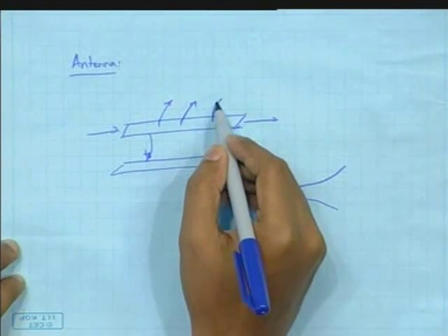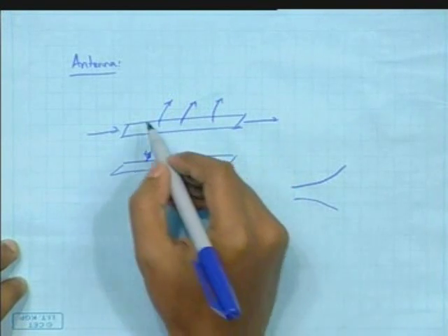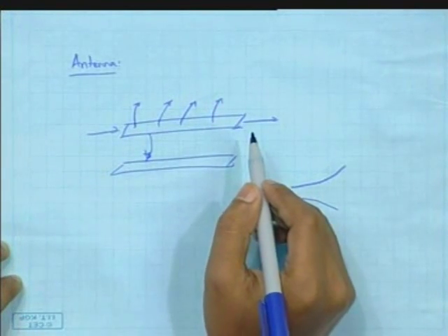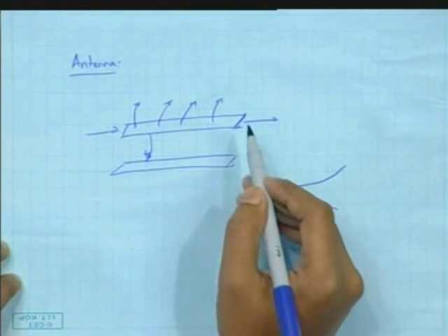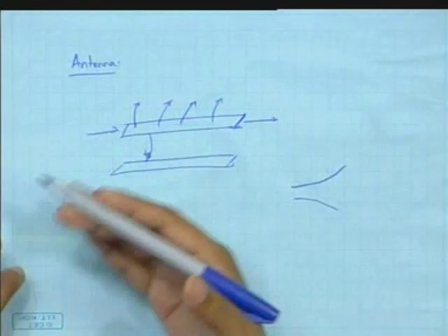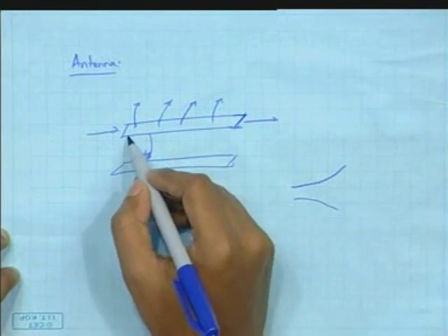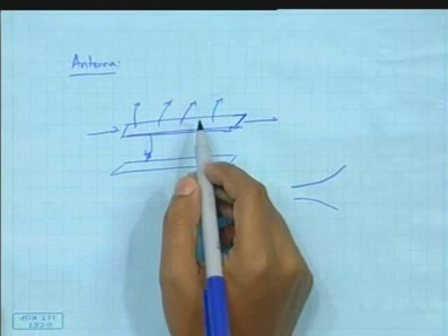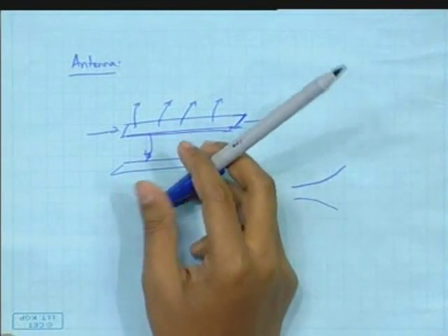So these types of antennas in general are not fabricated on silicon due to the higher dielectric constant of this material, and hence generally antennas are on a separate substrate, but it's on the same total package. So this is basically the summary of whatever microwave devices you will be using. You can have a brief overview, you will be studying, most of the electronics guys will be studying in your future classes. But it's good to know that when you design chips, at high frequencies you should be able to identify these effects, as not use very thick lines that will contribute to higher capacitance, and hence my losses will increase, the speed will decrease.